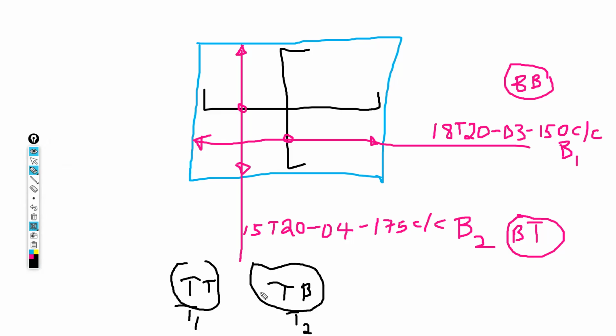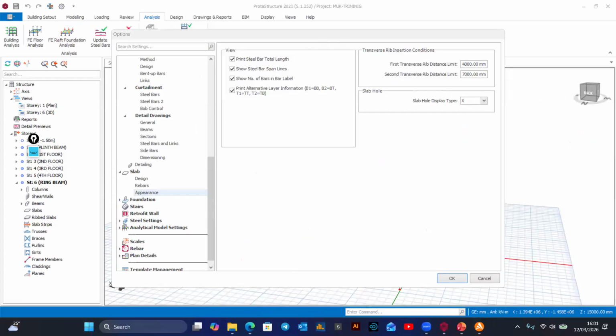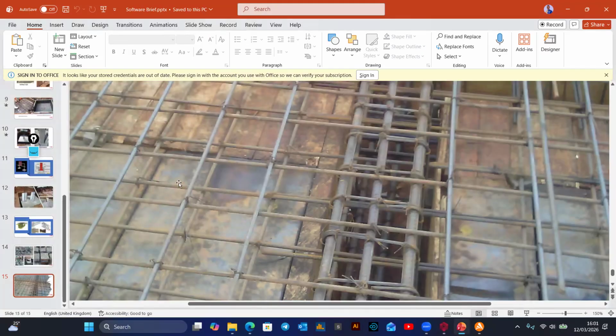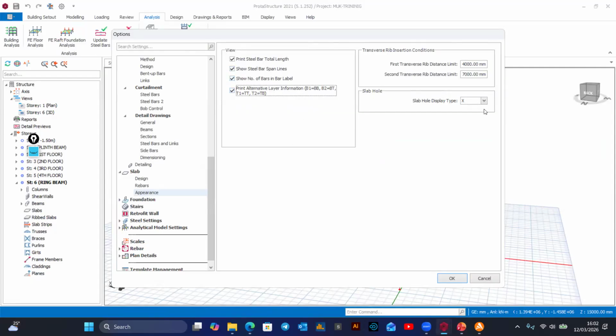What do they mean with top, and then top, bottom? We have seen that if it starts with the T, it's top reinforcement. Okay. So when you are looking at top reinforcement, one bar will be on top of the other. One will be below. So one which is on top, this is top. This is top, bottom. Then we'll go to bottom reinforcement. This is the bottom, top. And then the one which is right at the soffit is bottom. You get it? Eh? Okay.